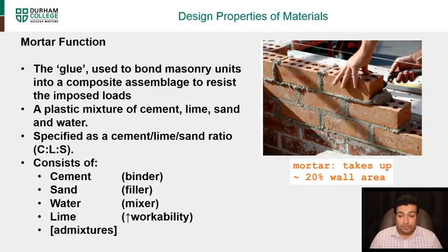of the brick. The mortar basically functions as a glue, and it is a plastic mixture of cement, lime, sand, and water, and is usually specified by the cement lime sand ratio, called CLS. It consists of cement, which is the binder, the sand, which is the filler, the water, which is the mixer, and the lime, which is put in for workability.